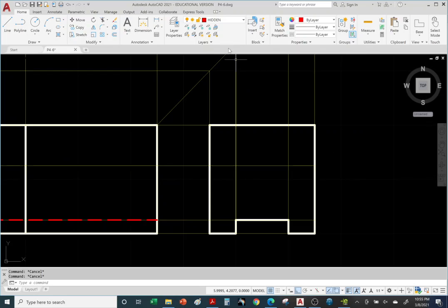Okay, so let's go to the visible object layer. Draw a line going diagonally across from the bottom left corner. Let me turn off ortho. There it is. I got more freedom. And snap to the upper right corner and right click enter. Okay, so there's our side view. Are we done? Let's go check.